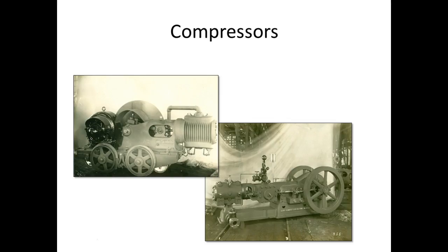So what parts do we have in a pneumatic system? We have a prime mover, then we're going to have a compressor. Then normally we'll have a receiver, or a tank. Then we'll have our piping. Then we'll have our control valve. We don't run an actuator without a control valve, normally. Then we're going to have some type of actuator. But this is what we're going to have.